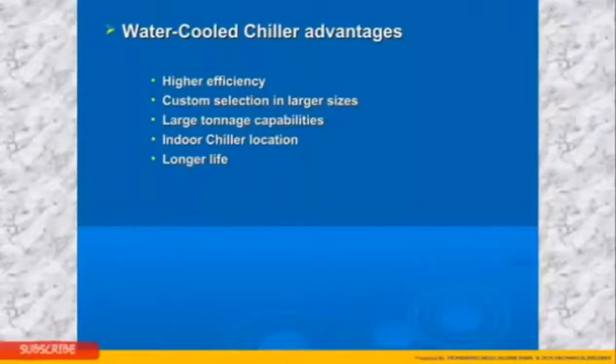Now let us see the advantages of water-cooled chillers. Higher efficiency, custom selection in large sizes, large internal capacities, indoor chiller location, and longer life. For sure, the initial installation cost for a water-cooled system is higher than another HVAC system. But in the long run, when you consider the lifetime cost analysis, this is the most efficient system as of now.